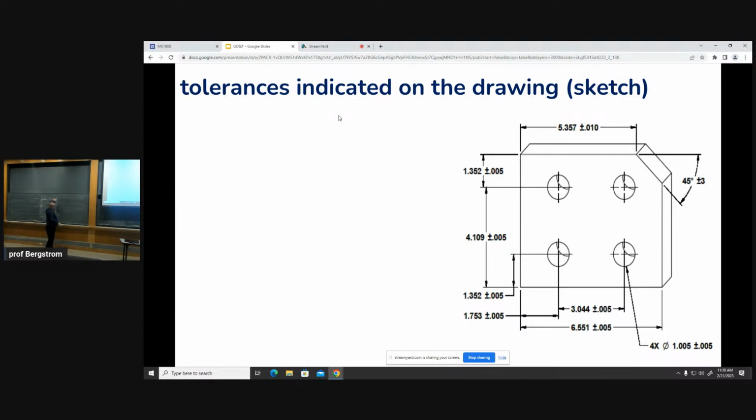Well, this is not a real dimension on the part, because if we add that dimension on the part, then we've over-constrained it, correct? Because if we add that dimension to the part over here, then the tolerances can't add together. Okay, so now that we've made our squarish part, now you want to make the holes?